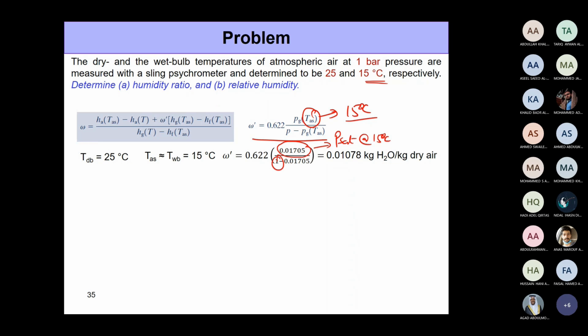Where do we get the 1 from? Well, it's the pressure of the mixture. It was given as 1 bar. Okay, so P by 1 minus P times 0.622, and this is the quantity of water vapor at the exit, or quantity of water vapor per unit mass of dry air. Now we want to do the same thing for omega, right? We actually want omega. We are not so interested in omega prime. The only reason we got omega prime is because we need that for calculating omega.